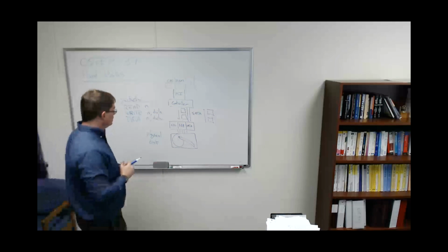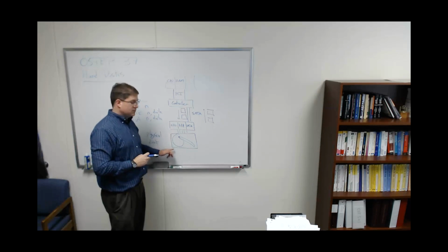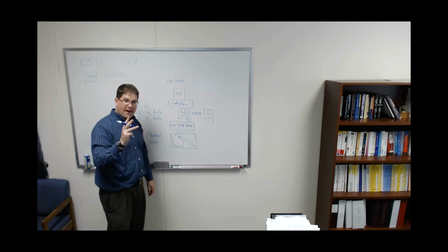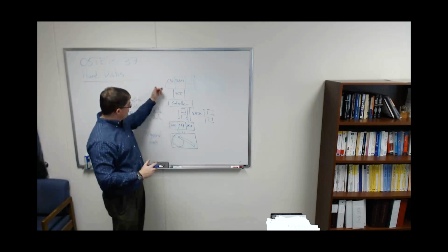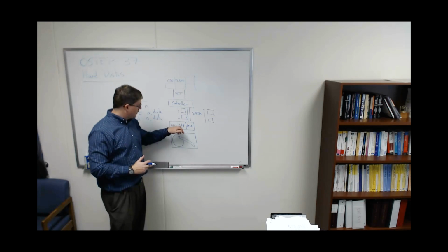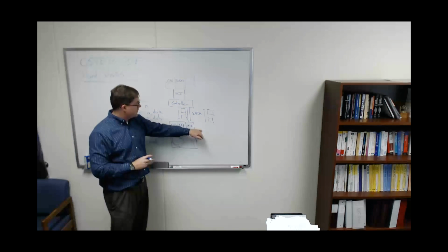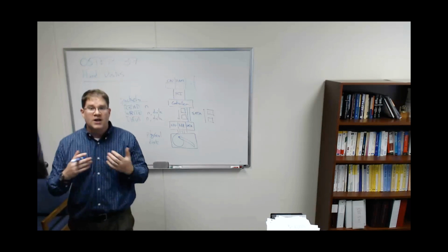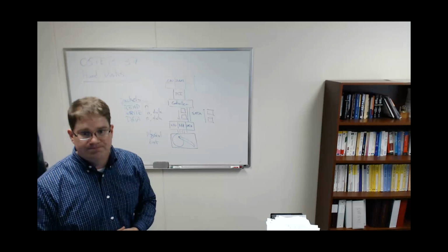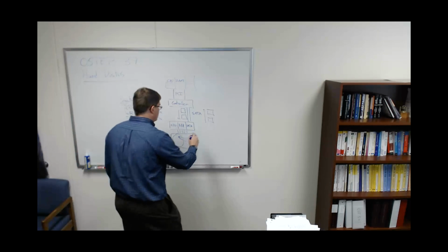Likewise, data becomes available on the disk at odd intervals, right? This disk is spinning around, the arm is going back and forth, and it's difficult for the machine to predict exactly when this data is going to come back. So when data is read out, it goes into this buffer here until there's an opportunity to send a packet back to the controller, and the controller is able to receive it. In other words, this whole process here is asynchronous.